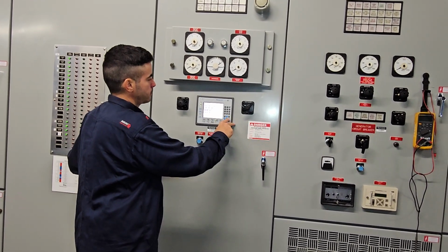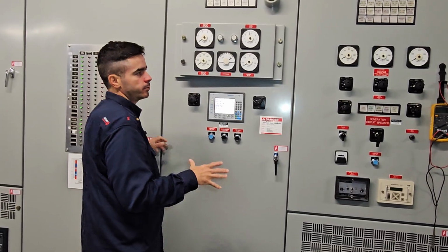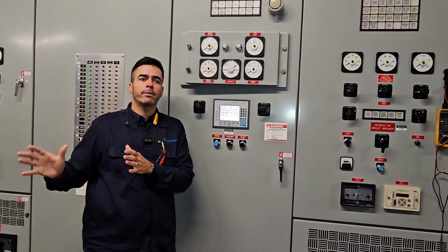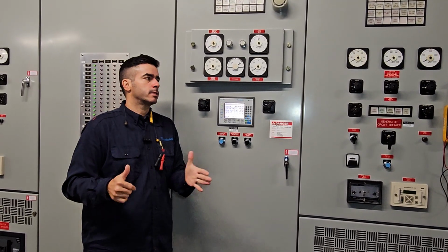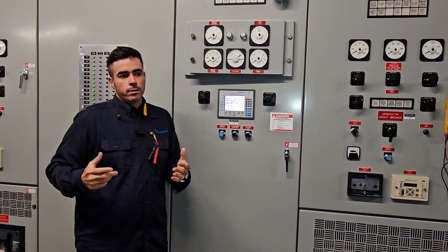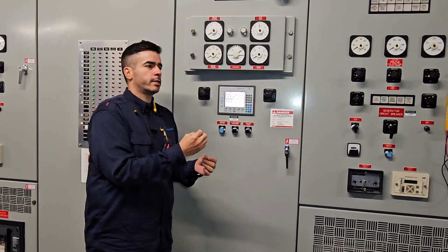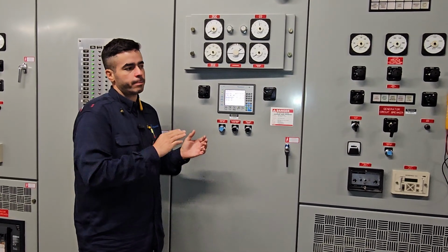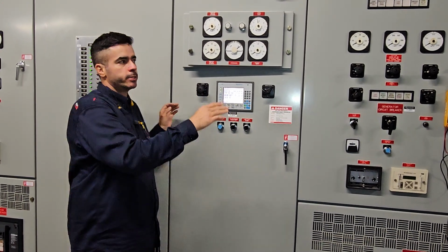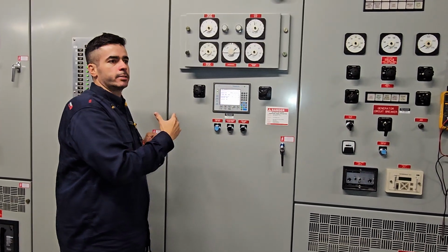Then we got some overload and under frequency set points. That is for load shedding. The ATSs have set some priorities. Priority 1 is the most important load that you have, like life safety and some critical loads. Those will always transfer as soon as the first generator is online. So that priority will never shed, right? If something happens, the generator is burning out, the load will be connected still.